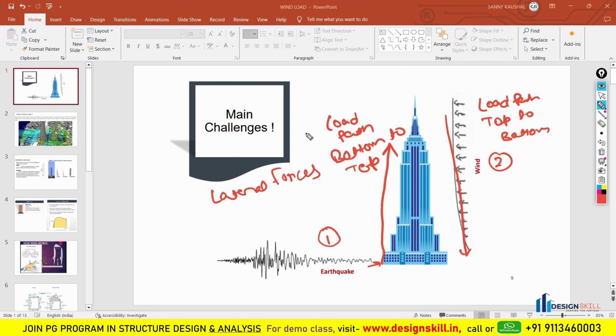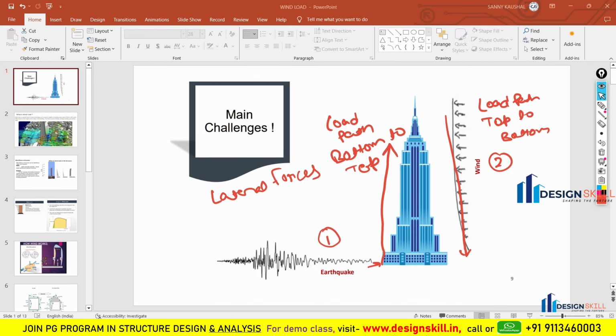So this is the major difference between the two forces. The nature is the same; both are lateral forces, but the load path, how the load is going to transfer in this building, is different. When an earthquake strikes, the load is transferred from bottom to top, but when wind strikes, the load path is from top to bottom. This is the important thing we have to keep in mind while designing the building, while considering the wind load and the earthquake.